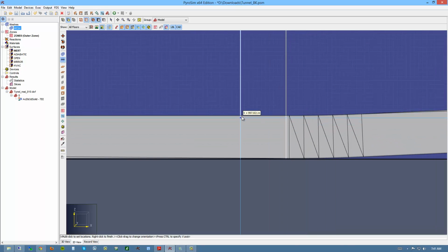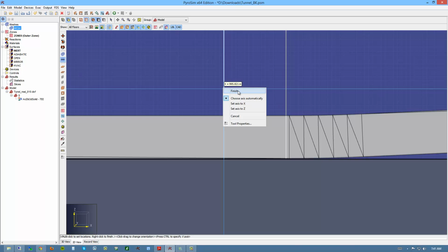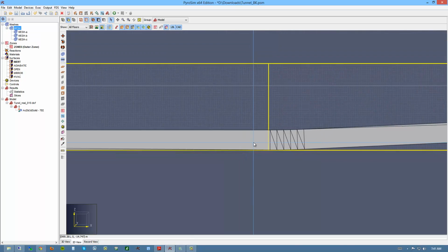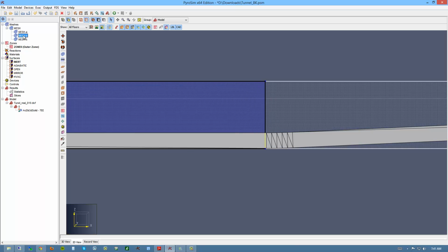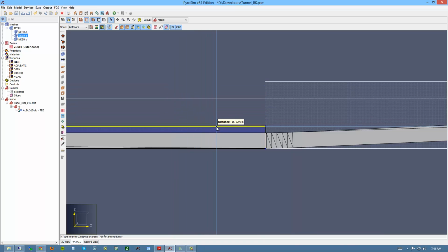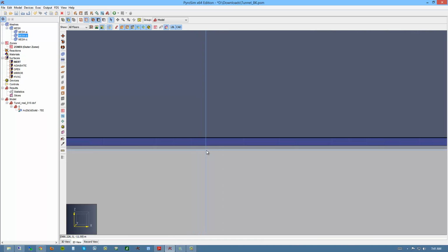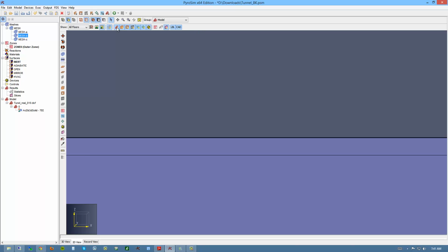And then let's look over here. We'll cut here. Okay, so now I right click and say finish, and I have 3 meshes now. You see mesh A, B, and C. Mesh B is the one that we want to change. So I'm going to pull this down to here. And let's see, yep, we should have just about one cell close, and if I preview, I see it fills that cell.